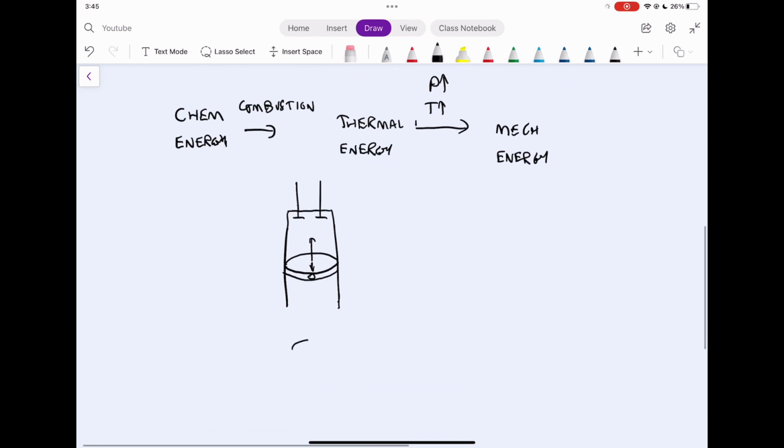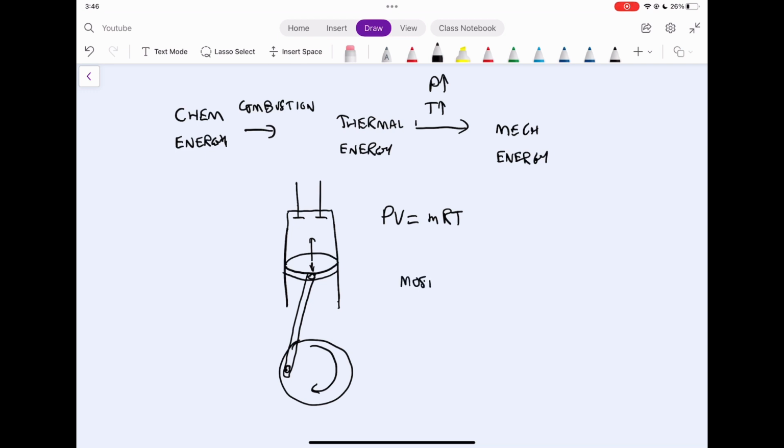We'll talk about the valves later, but essentially we have a piston moving up and down inside a cylinder, and it translates to a rotational motion at the bottom on some sort of shaft. We can use the principles of ideal gas as an approximation to figure out what happens to pressure and temperature within the combustion chamber shown above the piston.